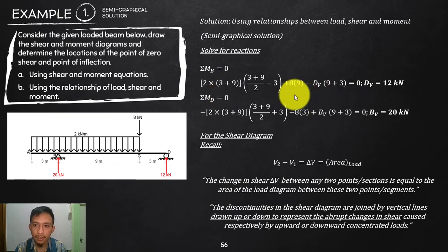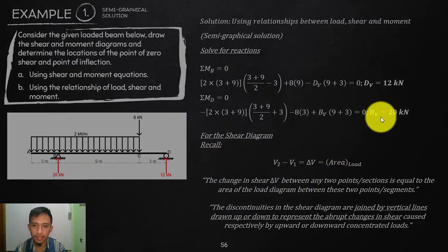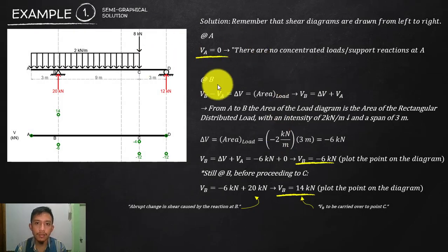Okay, so again, we established the reactions a while ago. These are our reactions. And then all we need to do is solve for the shear and then solve for the change in the shear. So that's what we are going to do. So let's start at A. The shear there is 0. I will cut at the very first point. There is no force, so that is 0. The shear at your A is 0.